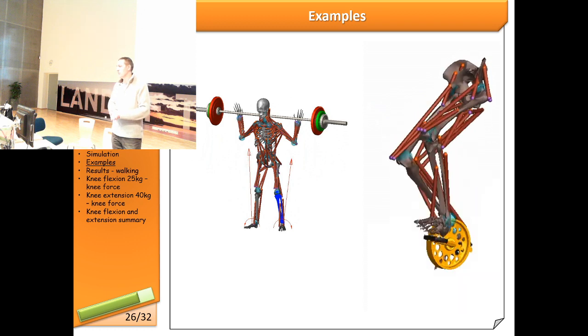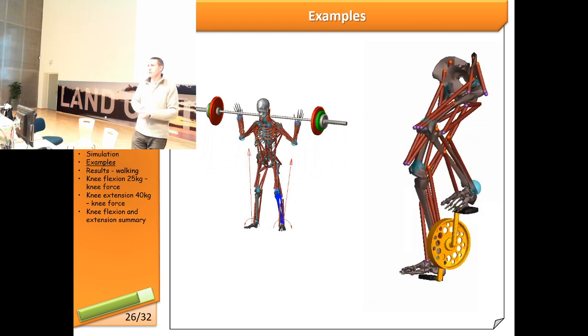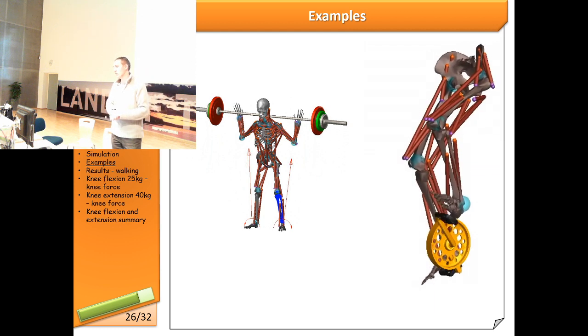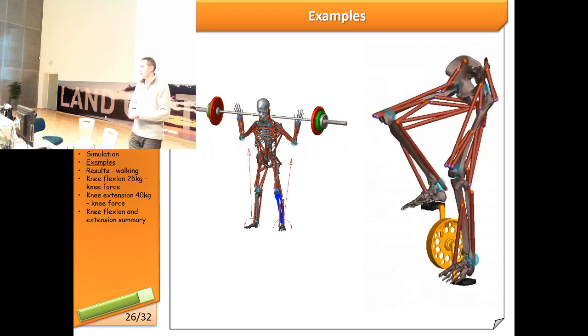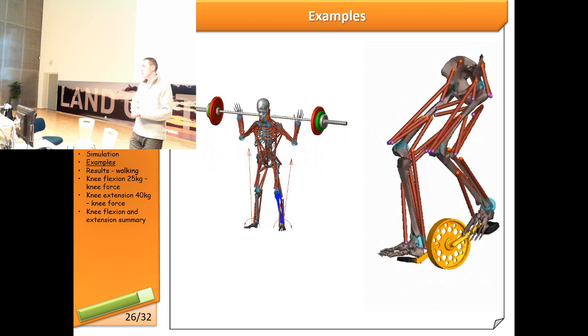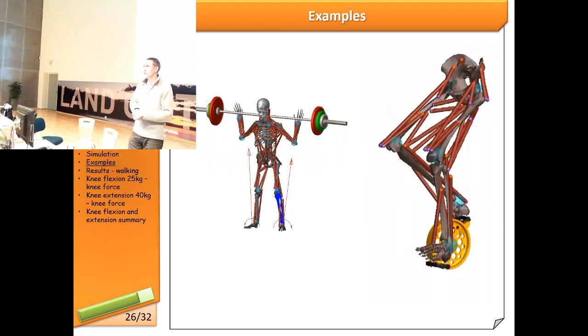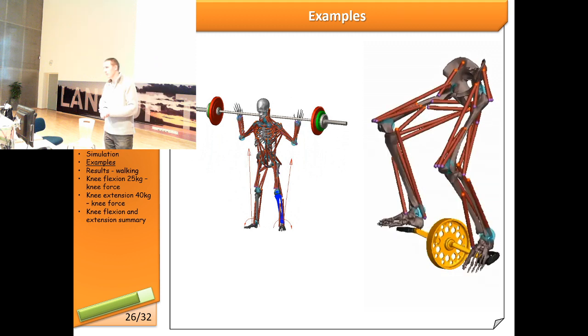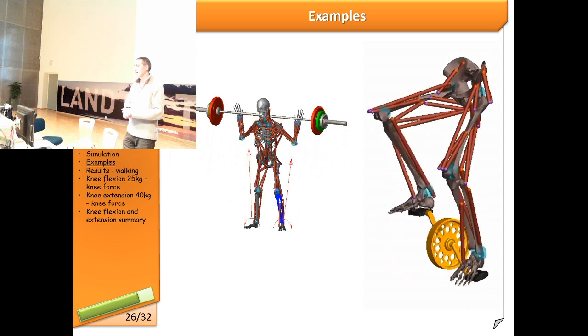But because we had the bodies modeled, you could apply the joints between the pedals and the crank and everything else, and apply torque to the crank, which is the limiting torque created by the cyclist. And what we did here, for example, to verify that, we put insoles in the shoes, which measured the forces, so we knew how much the guy was pressing. And because the guy had a history of being a football player or some other sport which is kind of asymmetric, we realized that even though from motion you could not see this, he was applying almost twice as much force on one leg than the other. And actually we could also see that later on in the simulation, which was quite nice.